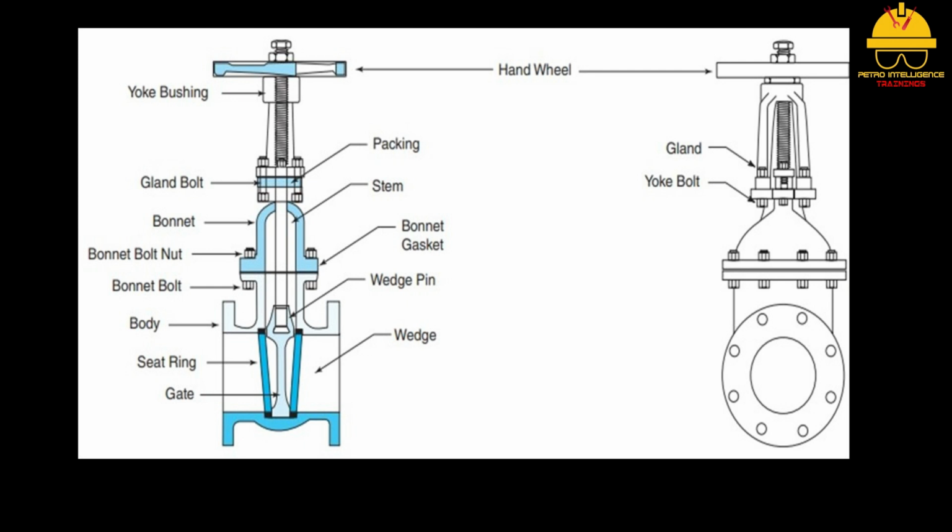The seating area falls into two categories, replaceable or fixed. Seats must provide a clean mating surface for the gate to seal properly. The seat can be fabricated or cast as part of the valve, press-fit, threaded, or welded into place. Note that high temperature and high pressure situations may require a combination of threading and welding.